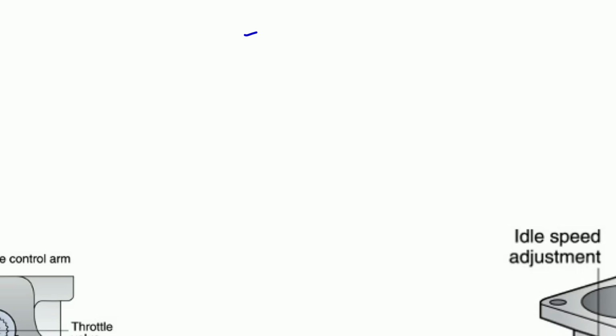So, starting off with our fuel system for a reciprocating engine aircraft. As we talked about before, our cutoff point for the fuel system when we're talking engine versus airframe is typically going to be wherever our engine driven pump is, or the strainer that goes into the engine driven pump.